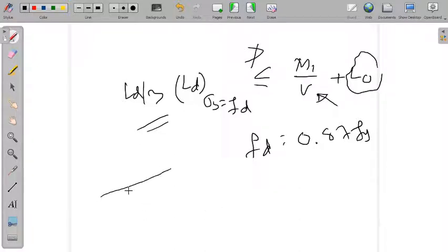Suppose this is the beam and this is your support. Your bar is continuously coming like that, and it will go like that, and then it can take a turn like that, or it can take a turn like that. I will tell you what those things are. So this is the center of support. It says the sum of the anchorage beyond the center of the support and the equivalent anchorage value of any hook. This is one hook, a U type hook.